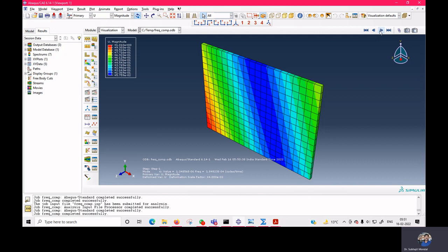Since we do not have any boundary conditions, the plate will exhibit some rigid body motion, and that is what is showing. Okay, so there is nothing to worry about, and the analysis is not wrong. Till now our analysis is not showing some erroneous data. That is as per our expectation. Since we do not apply any boundary condition, it will show rigid body motion. So here all 6 are rigid body motion.